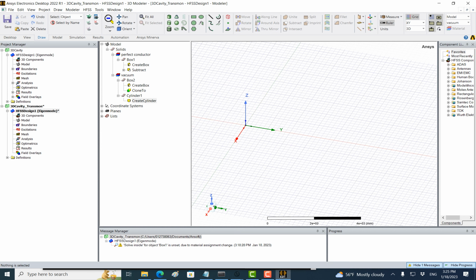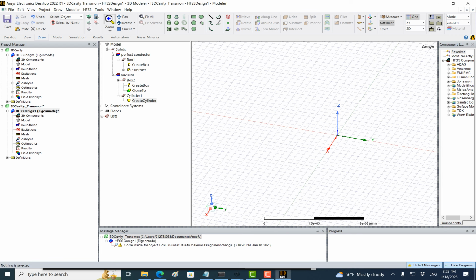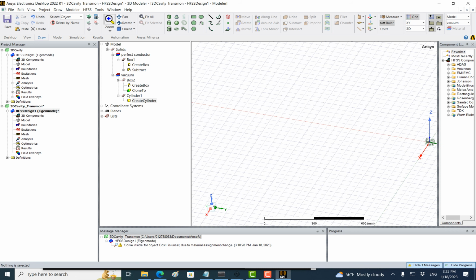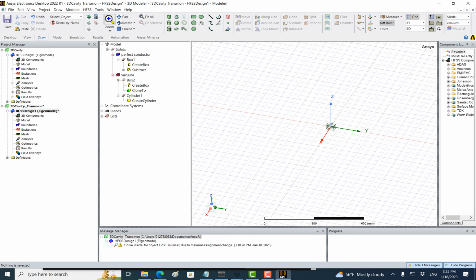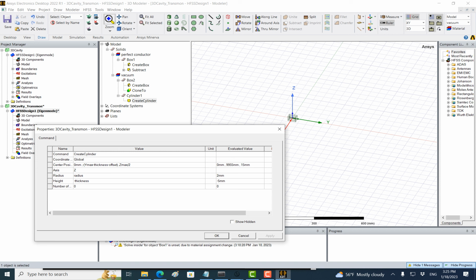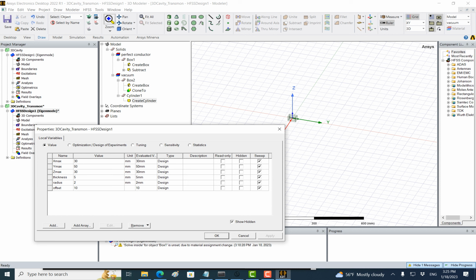Okay, so what I need to do, just click shift and drag this, and then control plus, or actually control equal, not plus, right? And then drag it. So I made a mistake. Let's see, but that should be easy to debug because it gives you the value. You see that this is 9955 millimeter. That is wrong, right? So maybe I put something wrong in my offset, I guess. Maybe you saw it already. What is my offset? It needs to be millimeter. I forgot to put the millimeter.